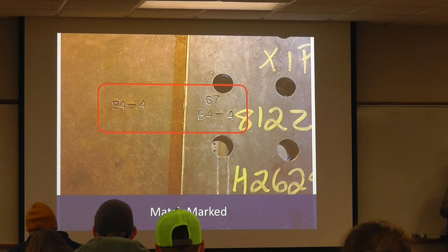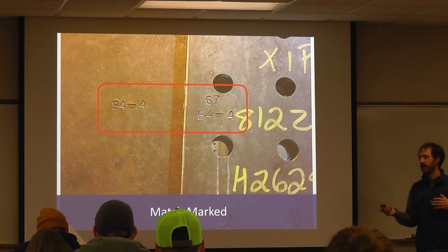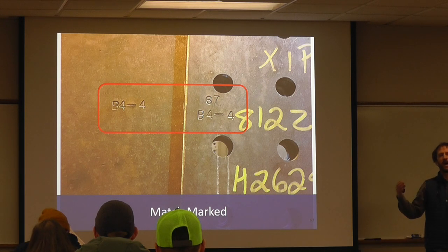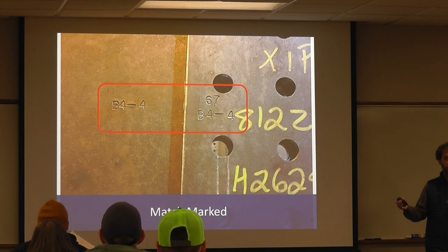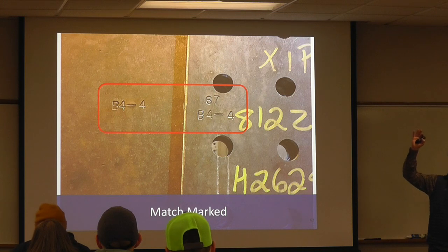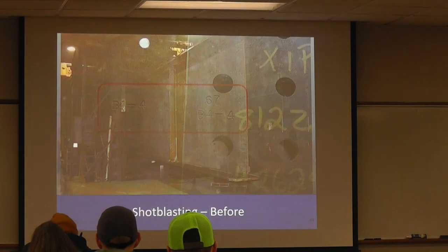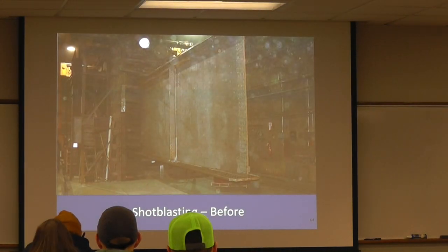So when girders get painted, they have to be shot blasted before the prime coat gets put on. And so oftentimes you have 2 separate operations in this. Generally, these splice plates are smaller elements and can be taken somewhere else in the shop and blasted, where the girders are going to be blasted through a much larger system that takes up more space and more time. So to be efficient, they're going to move things all over the shop. So here you can see this is a girder going through a shot blasting operation. And because they get separated for a moment, if the folks working in the plant aren't paying attention, that's how that stuff can get mixed up.